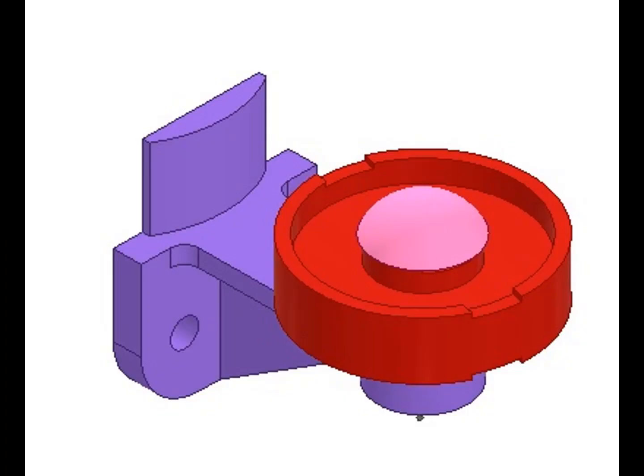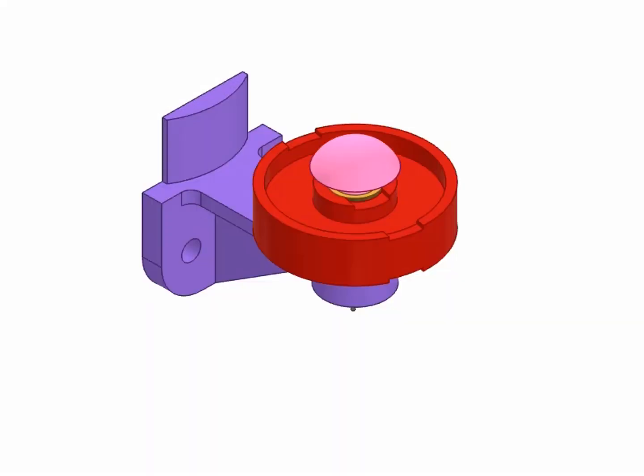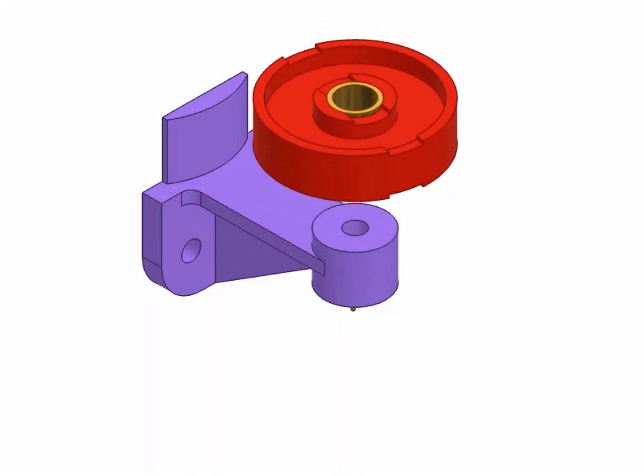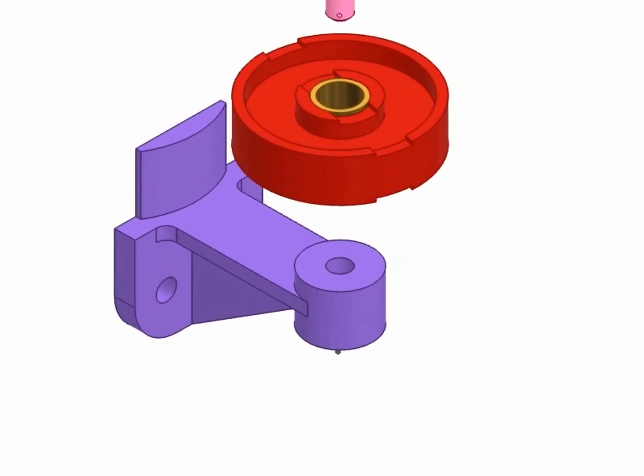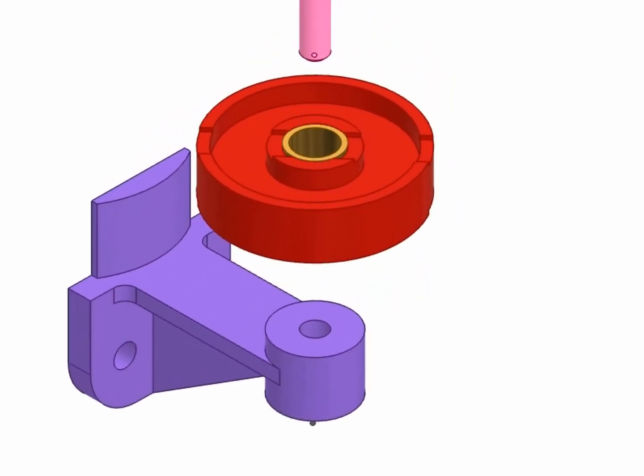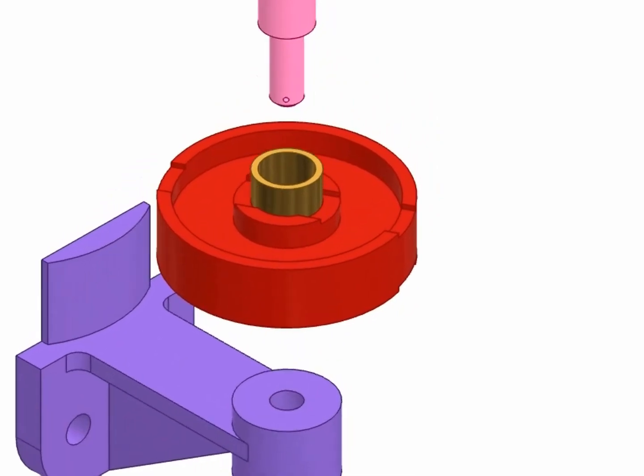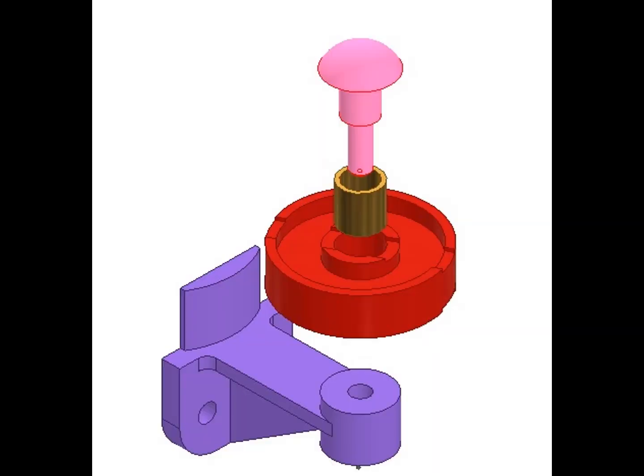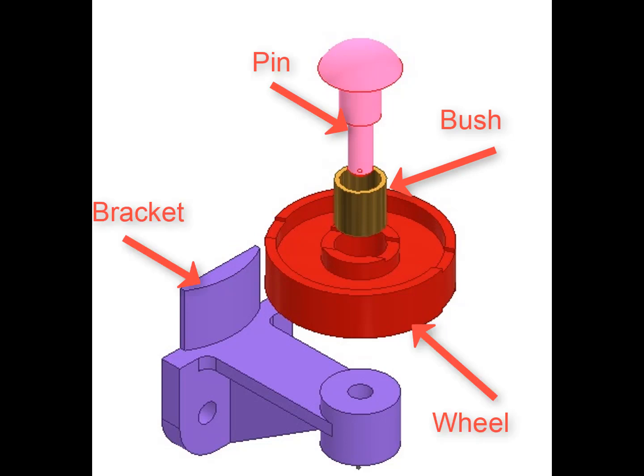Let's give another example about tolerance. We will examine the tolerance between a sliding door wheel, the connecting pin, bush and the wheel connecting bracket. Here, the wheel number 2 and the bush number 3 are connected by a tight fit and turn together. The connection between pin 4 and bush 3 is a clearance fit condition which allows the wheel to turn. Our common part is the number 3 bush in this assembly. However, it has to have two different tolerances in terms of functionality.